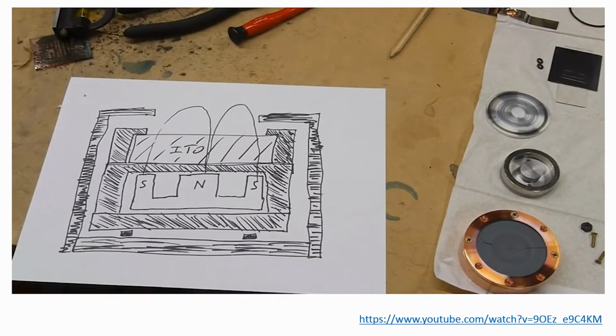It seems in the literature that most people prefer 10 to 100 millitorr for proper sputtering pressures. But it's also very common to use the diffusion pump anyway and pump the chamber way down as low as you can get it, basically just to clean everything, to get the water molecules and everything to evaporate off the surface, and then backfill it with argon back up to the pressure that you want.